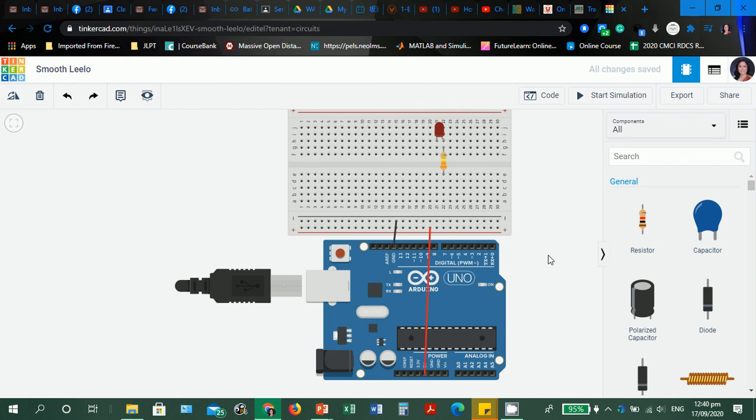How are we going to wire this to connect? Of course, as I've already said, since this is the anode, it should be connected to the positive or the 5 volts, or to the source. So let's create this point and then click it in here to the positive.